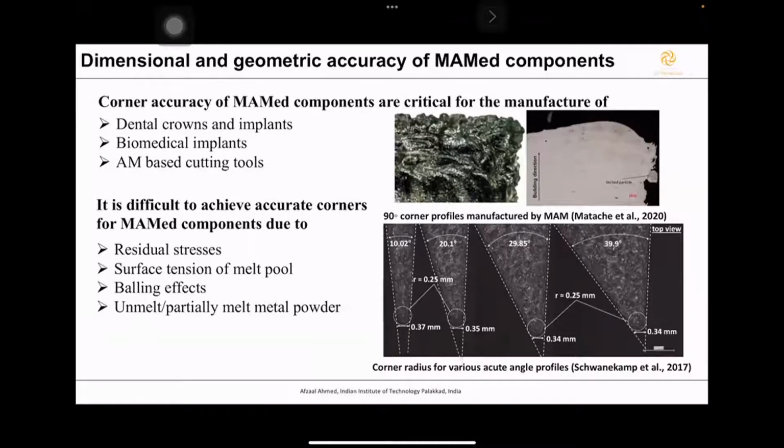In that particular period, the temperature gradient in the atmosphere inside the chamber and on the surface of the printed layer is very high. So local super elevation on the layers may also happen, or warping of the layers in common terminology.